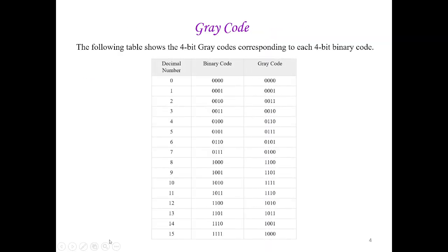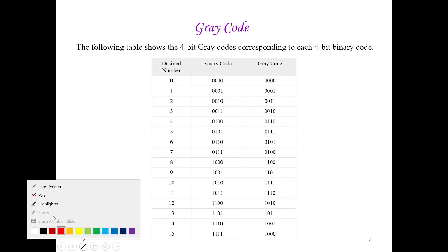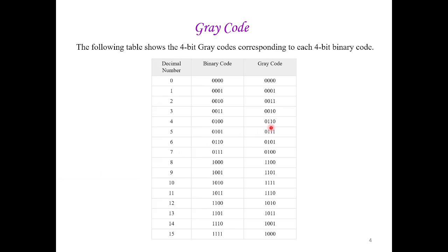So gray code to binary conversion, that is day 3. So what is a gray code? Gray code is like this: this is the decimal number and this is the binary representation. Each and every code differs by 1 bit position, that is gray code. So if you see, the first code 000 and 001 differ by 1 bit, and 001 and 011, so the second bit differs.